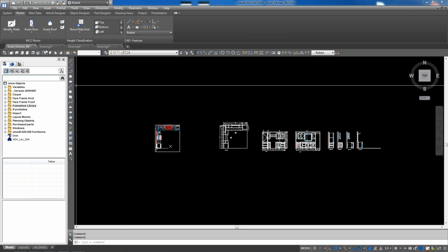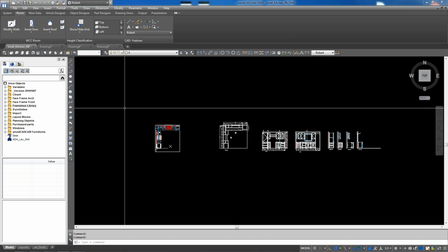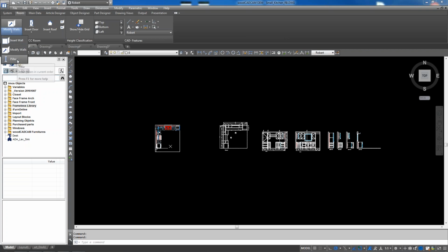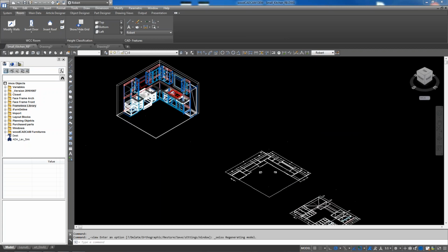Then my other question was how to add soffit, because I tried to use soffit as walls, but it didn't really work. I was having weird shapes. So then I used pillar, and it worked okay. The only thing is that I'm not sure if this is the proper way to do it. Yeah, so really the easy way to do soffits is to go to Part Designer.